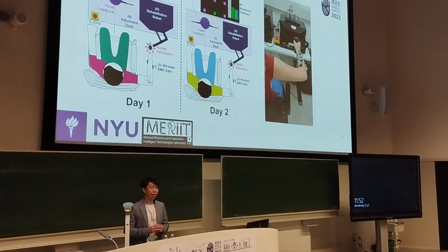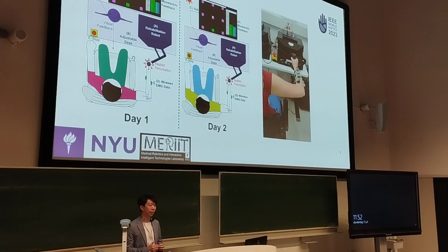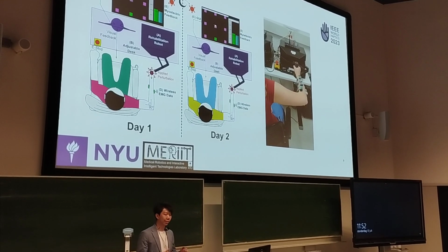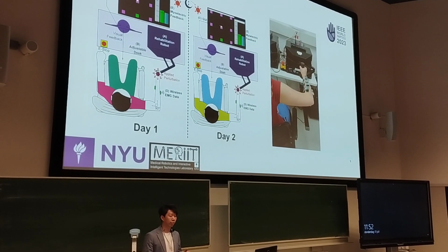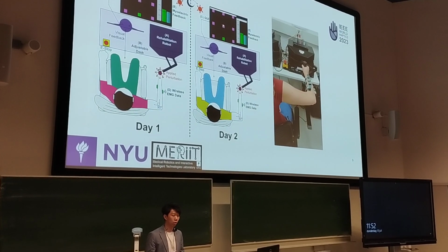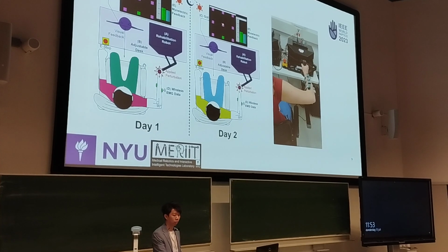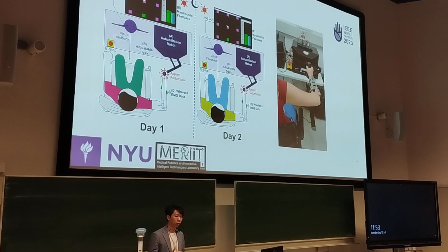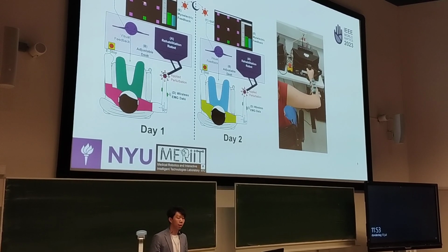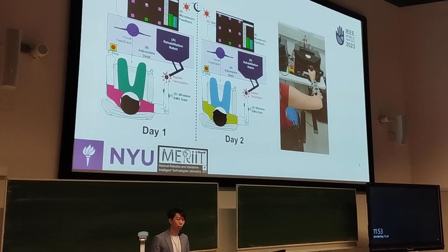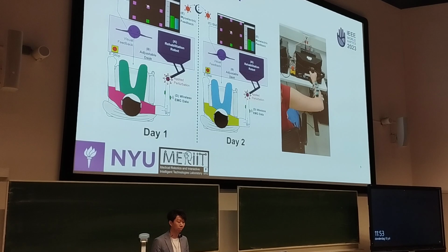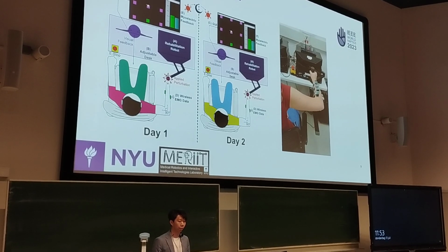So we have created an experimental setup to measure the excess of passivity of the participant in our study. The participant is seated so that their elbow makes a 90-degree angle when holding the handle of the robot at the indicated center location of the GUI. And the electromyographic, EMG, sensors are placed on the arm to measure the muscle contraction level of the forearm. These are processed into two bar graphics showing the percentage of muscle contraction compared to the maximum muscle contraction of the forearm.